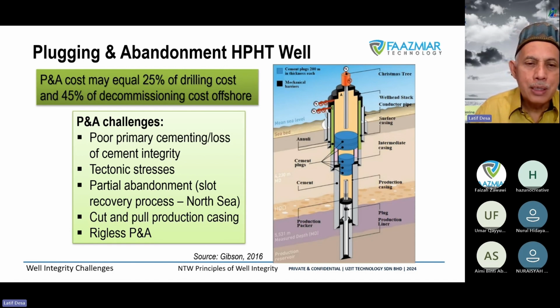At the same time, when we talk about plugging, because of aging, we plug the well after 15 or 20 years, and the corrosion condition of the well will be very bad. So we have issues to manage our integrity before we finalize our plug environment, because it involves management of high pressure in this area, and at the same time the temperature.